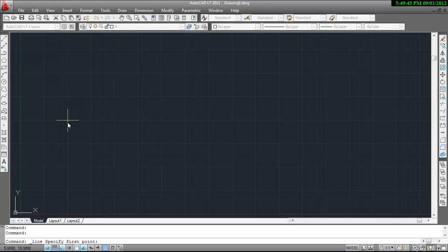How to create a line? Now to create a line, as you can see here on the command bar, it is asking about the first point of the line. You can give any point. As you can see, if I move the cursor here and there, this gives the position of my cursor in the coordinate system. So you can use that also, or I am randomly giving this point as the first point. And here you can see that it is asking about the next point.